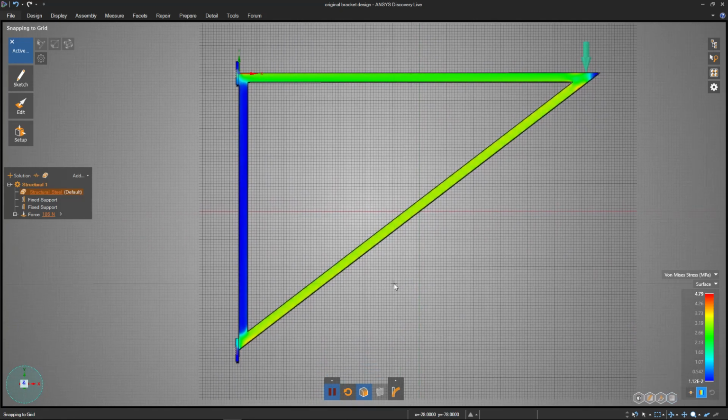With the line tool, I'm going to begin maybe just in this corner, and I'm going to try to outline this entire bar. So from that corner, I'm going to go straight down. I'm going to follow up along this edge to there. It gives me a nice guideline, so I know I'm right at the bottom. I'm going to go over to this corner, and then one more line closes up that shape. As soon as it's an enclosed shape, it stops the line drawing tool, so I know that's done.